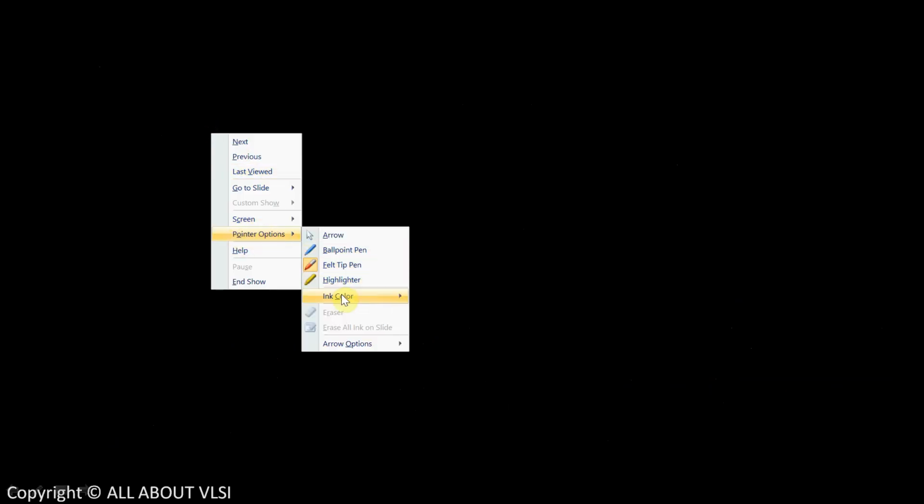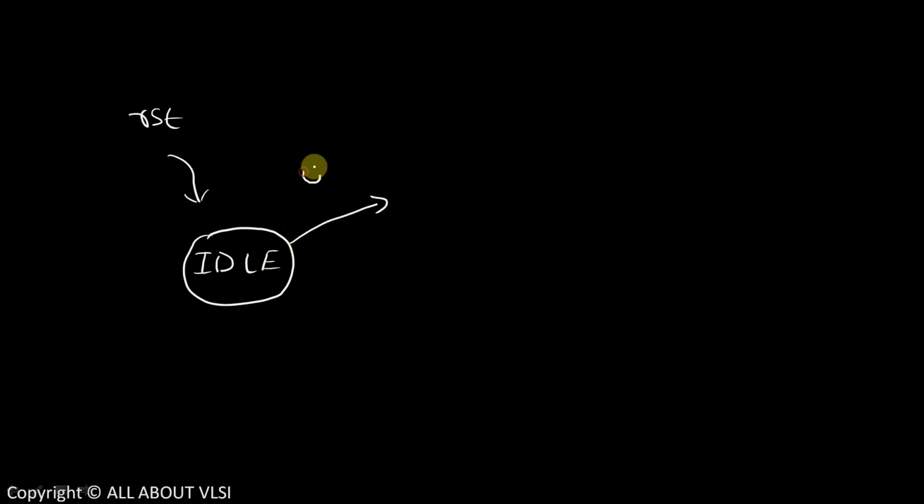So let us try to design the sequence detector. First, let us design the Mealy sequence detector. Then we'll come back to the Moore sequence detector. So, Mealy non-overlapping. Let us try to design this. Let's say we apply the reset signal, we simply come to a state known as the idle state, where no bit has been detected. Now if we are in the idle state, we have two options: either the input is 0 and the output is still 0, or the input is 1 and the output is still 0.